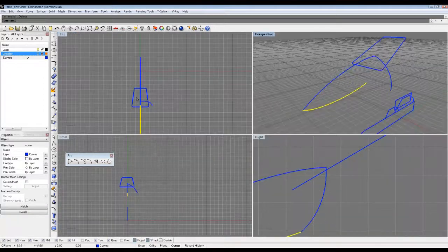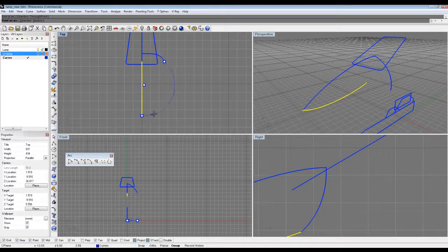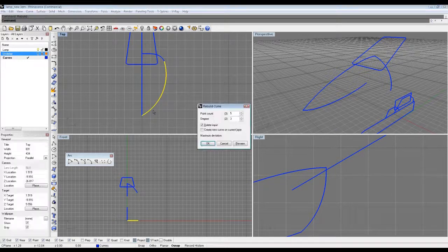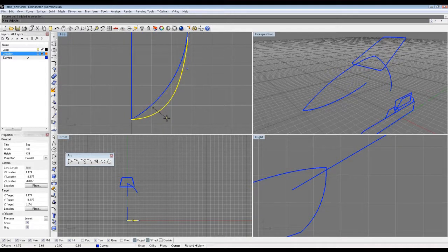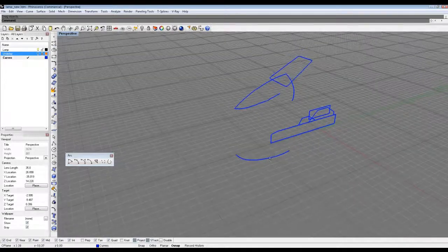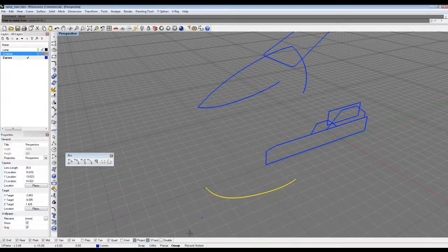the top view curve. Now I didn't draw the lamp top view curve, so we're just gonna arbitrarily pull out a curve here and rebuild it to something that looks good. And that, you know, that's sort of an aesthetic preference thing. So from what we're looking at in the top here, that looks about right. I'll move that with project turned off.